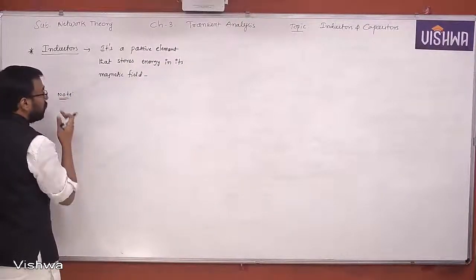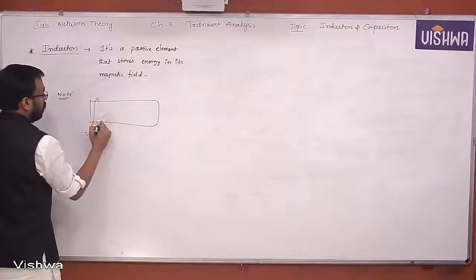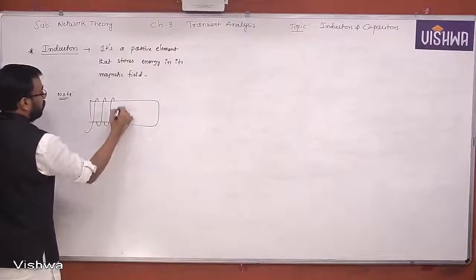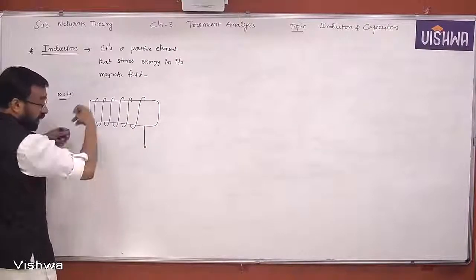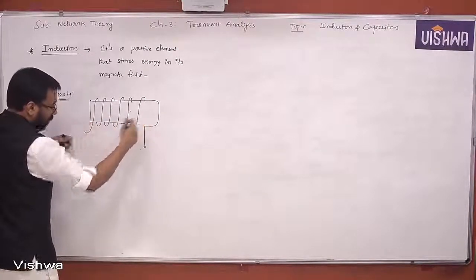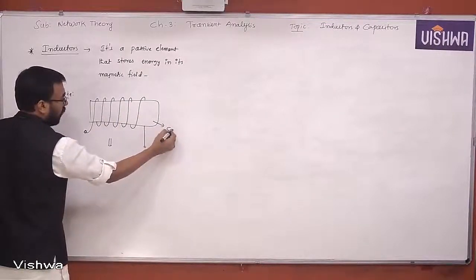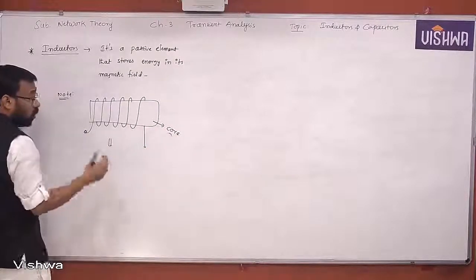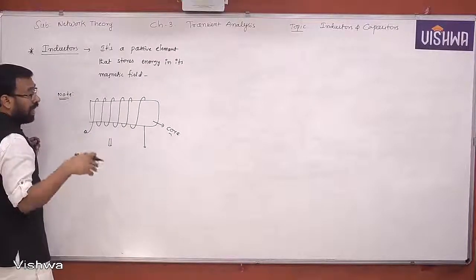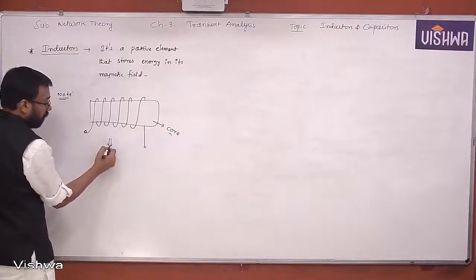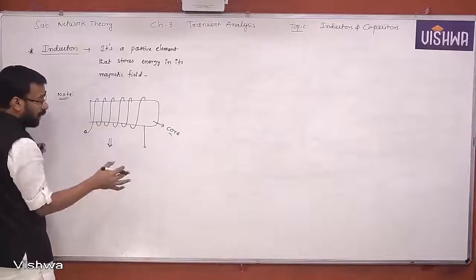So it's something like this. What you're trying to do here is take the wire and form it into a cylindrical coil, thereby forming an inductor. Now this is nothing but the core. A magnetic core you can use. That core might be anything: an air core, an iron core. Depending on the requirement, we go for the core, and how we design the core is a special topic.